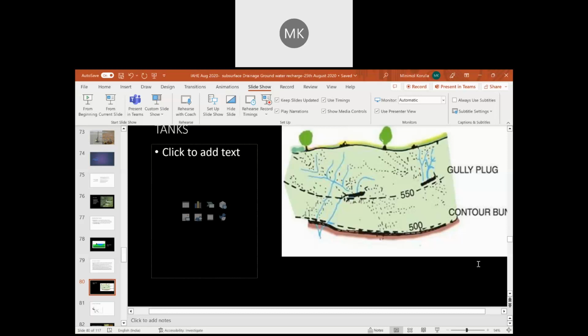Now when it is coming to a man-made retaining wall, between the retaining wall and the original backfill strata, we may be introducing a chimney drain, okay. So the illustration, the drawing which is shown in the right side corner, is a reinforced soil slope or a reinforced soil wall, where you can see the reinforcements are going within the soil, and the front face, the lower block, will be having a gabion fascia, which is completely free draining.